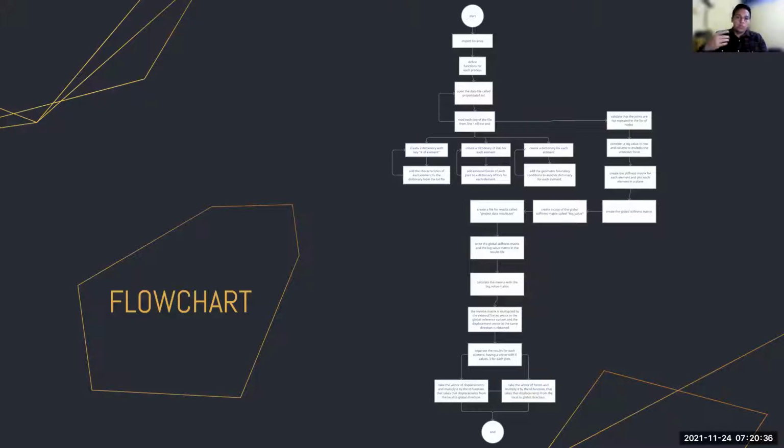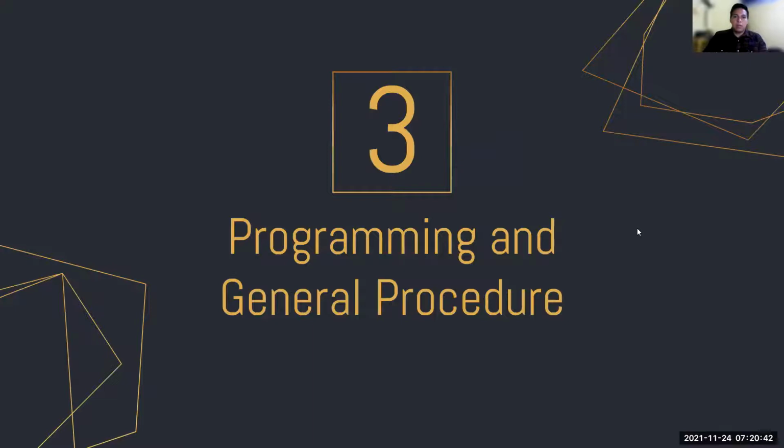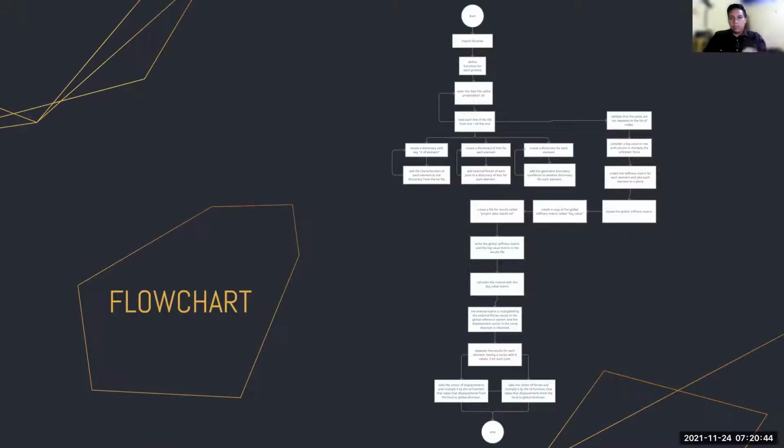Then we take these values to calculate the global stiffness matrix, get the main diagonal and change the value to avoid a singular matrix. Then we have the inverse matrix and get the displacement for the global reference system.